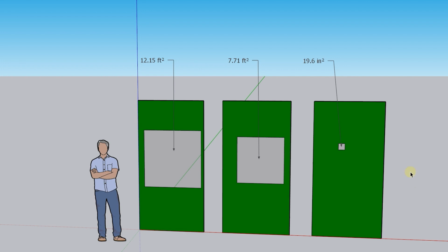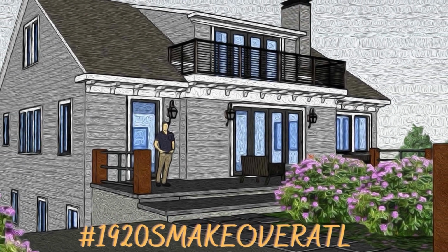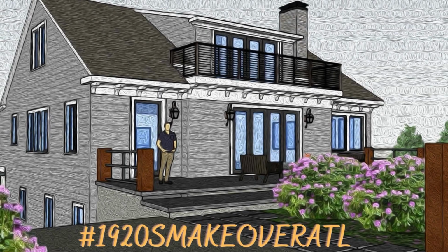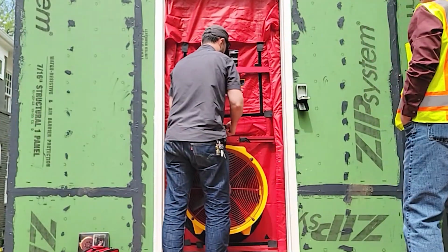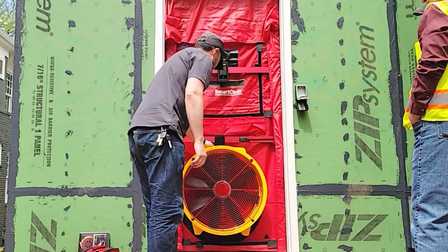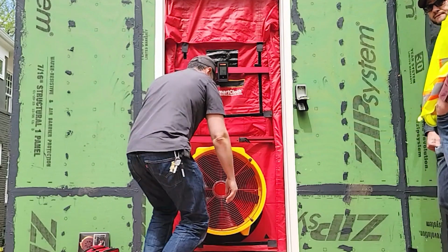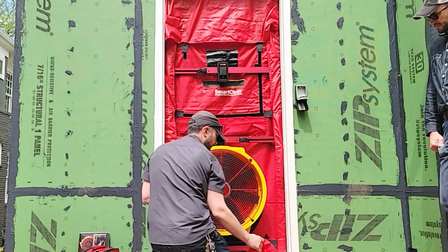Now this video is part of a series on air sealing and insulating, so definitely check this out. Check out the house that we did this experiment on. This is not usually where you do a blower door test. We did the blower door test at this point to show the difference between what a house was like with no sheathing, adding sheathing to it, and also adding the sealant to it, to show that sealant on the sheathing makes a huge difference.